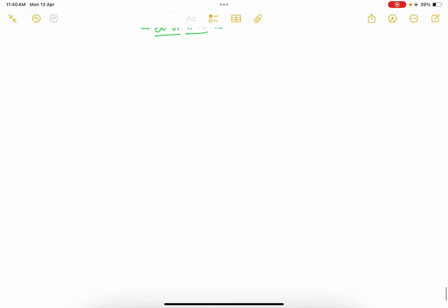If you see the structure of the JK flip flop, it is similar to the SR flip flop. First we make a cross coupled configuration, and this will be your Qn, this will be your Qn bar, this will be your Qn plus 1 the whole bar, which is the next state, and this will be your Qn plus 1.